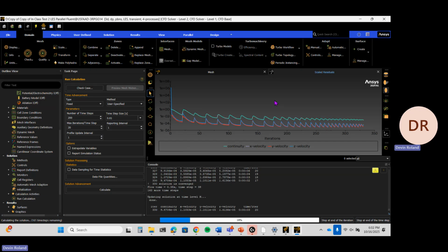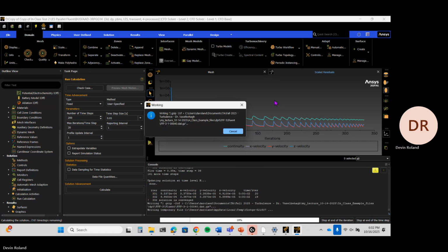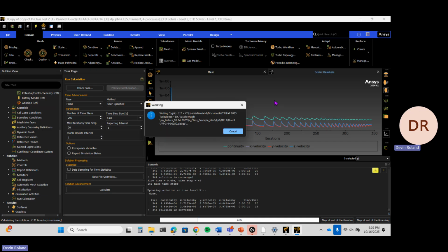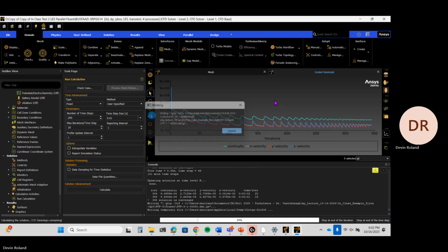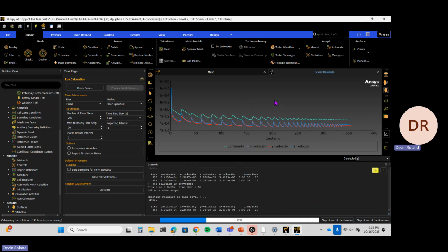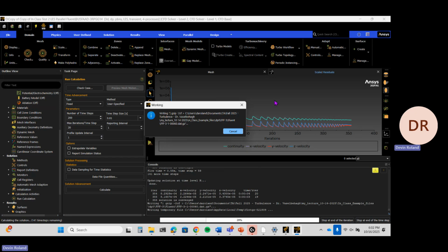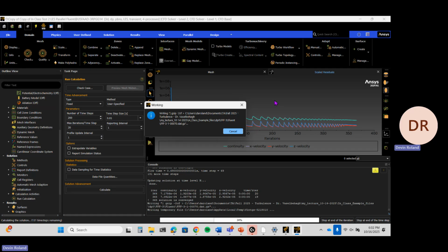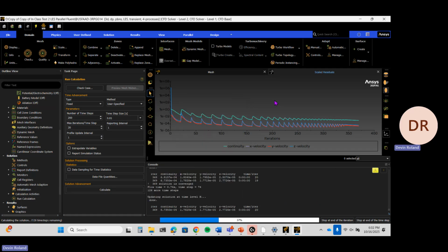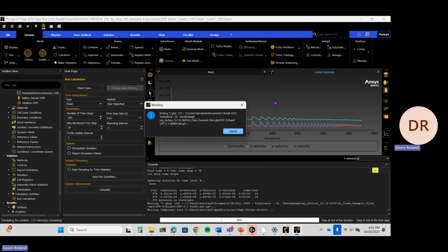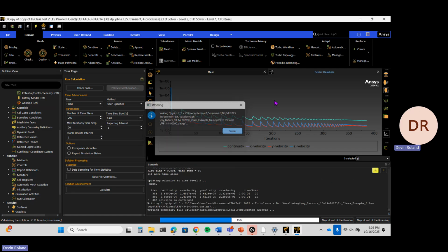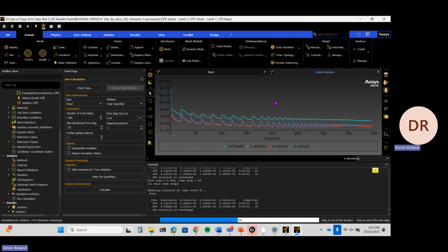Resolve meaning that if your eddy is like this big, then you have at least 4 grid cells to resolve the motion like this, let's say. So numerically, it can represent that swirling motion because the grid cells can cover that vortice.